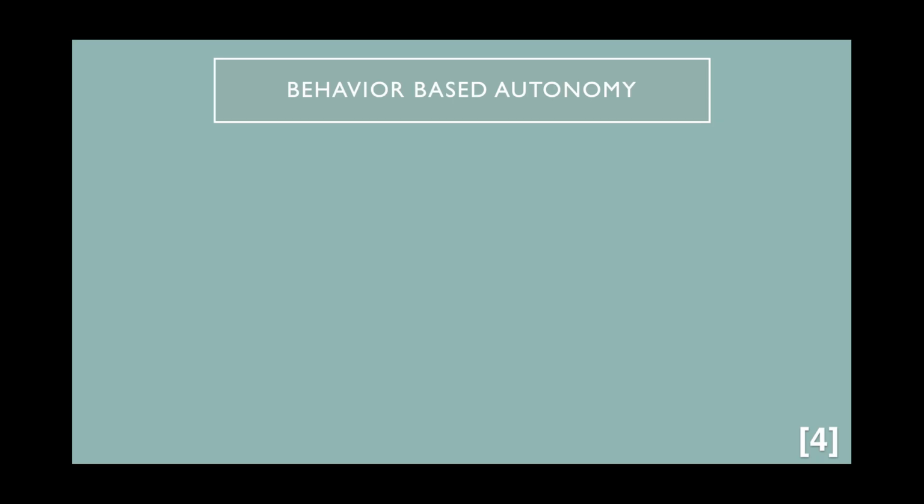That's where he started to rethink the traditional robot architecture into designing the behavior-based architecture. This architecture is based on the most simple animal behavior, the reflex. A reflex in this case means a direct connection between the sensor and the actuator without difficult processing in between.